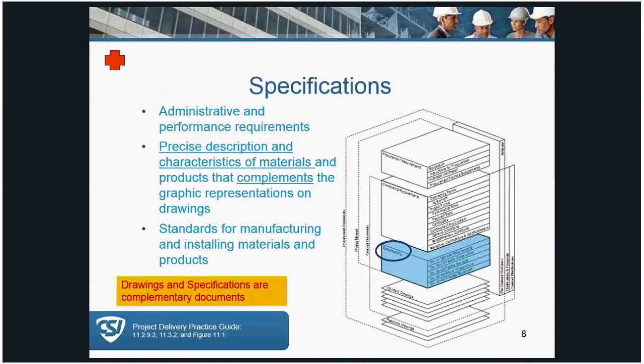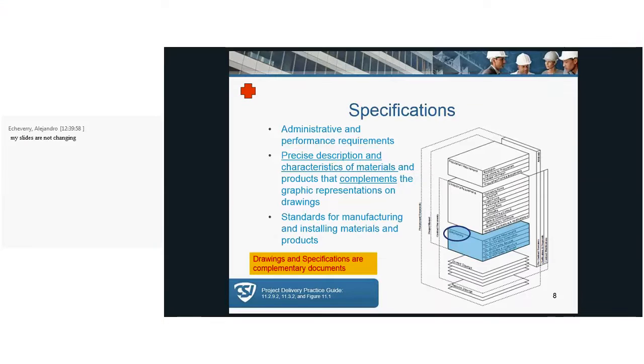And the 4th type, which actually can be 4A or 4B, or sometimes they call it a 5th type. The 4th type is proprietary, which means you're calling out that specific manufacturer's product. And it can be what's called open and closed. Open meaning that you'll accept substitutions, or you'll accept alternate manufacturers that you may have listed, or closed, which means that this is the only product you want. Keep in mind that specifications often use more than one type or method of specifying a particular product.